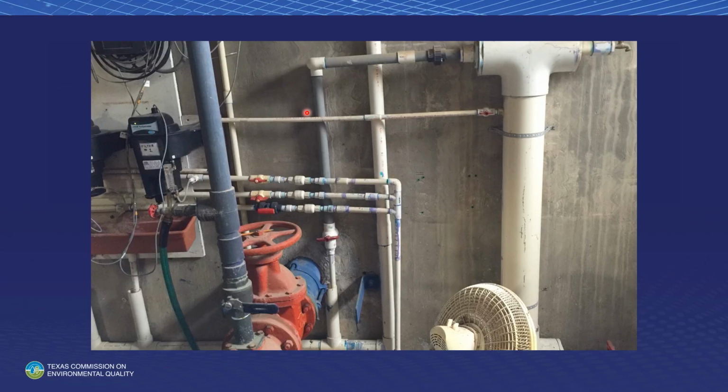But this is what's really interesting. See this column right here? This contains a combined filter effluent. All 3 of these filters have a tap that feeds the turbidimeter for each of those 3 filters. All 3 filters come down here, and right here, they all combine into a single line that goes down and taps into this 6-inch line that goes up. And here is the sample line for the combined filter effluent. They call this a CFE sample point, okay?